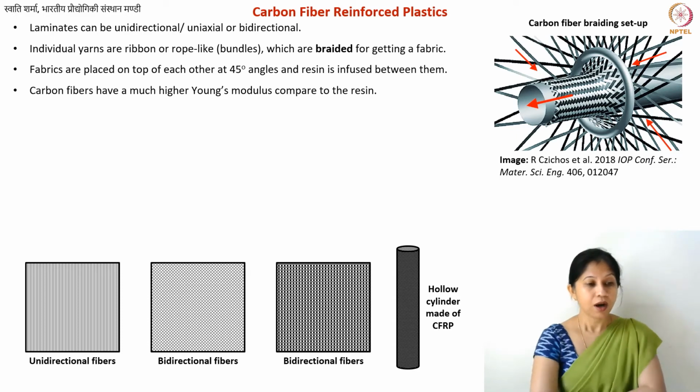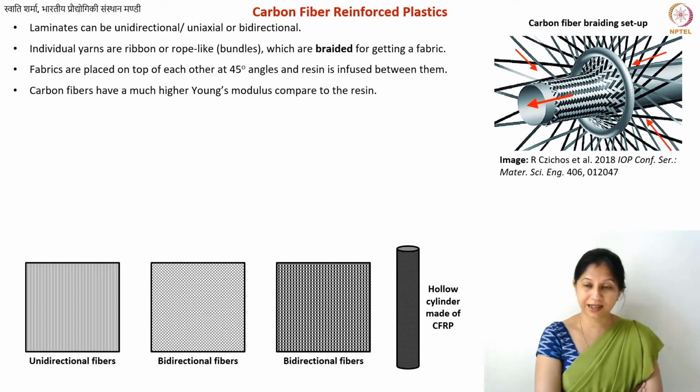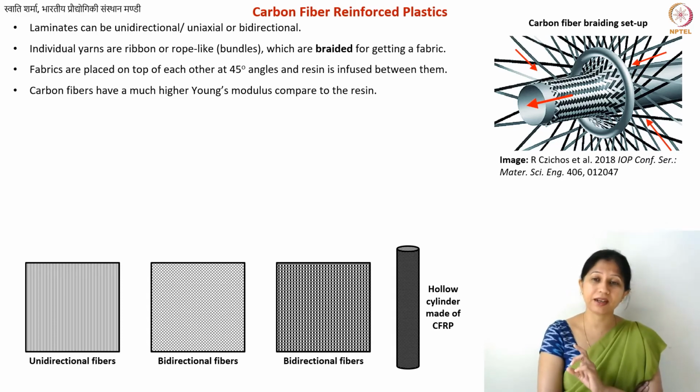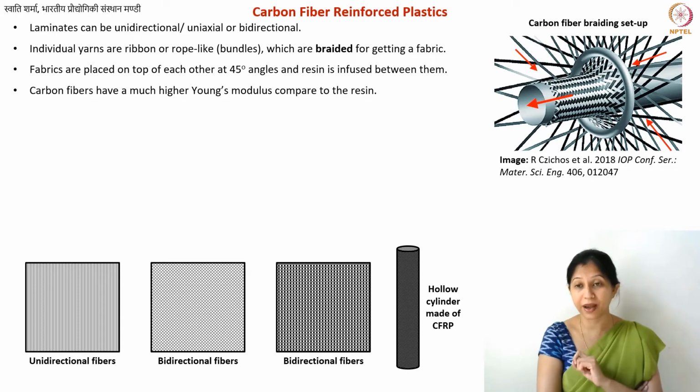Okay, now I think I mentioned before that it's the additive that carries the mechanical strength. So definitely the mechanical strength of carbon fibers is several times higher than that of the resin. But the density of resin is typically slightly lower than that of carbon fibers. So they make them lighter. But anyway, the difference in density is not so much. The point is that the mechanical strength of the carbon fiber actually reduces when you mix the fibers with the matrix.